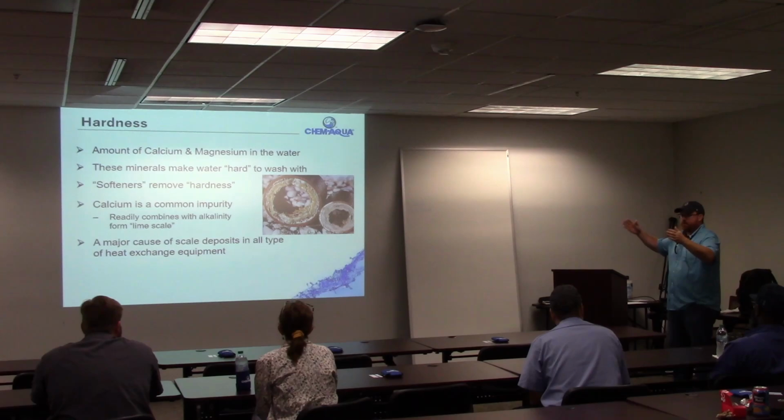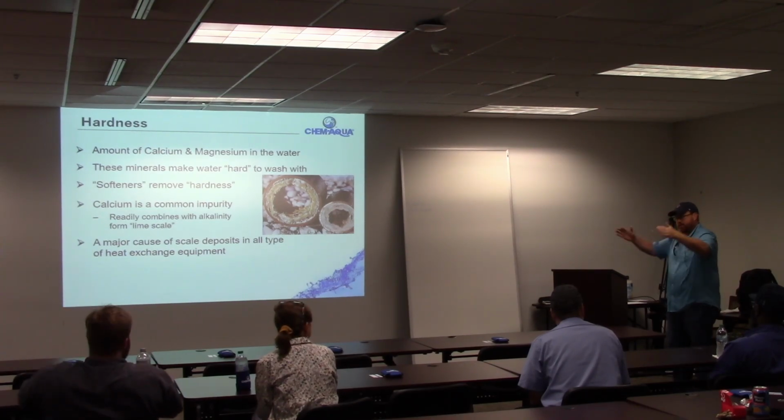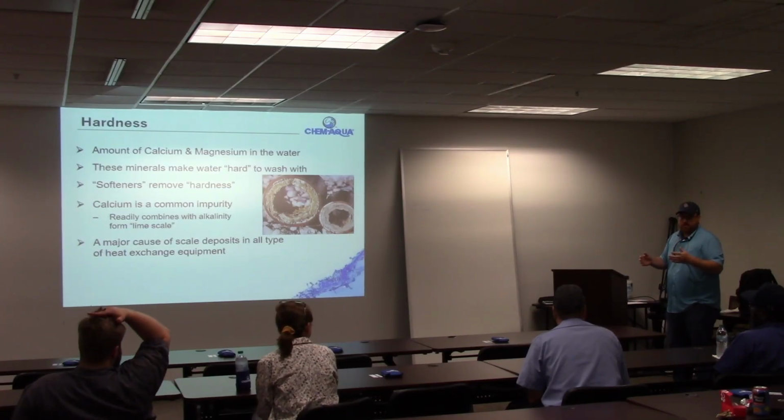If the fan speed is full out, that water curtain going through the fill is going to be pulled inwards. As your load drops off, that water curtain goes back out because the fan is not inducing airflow at as high a rate. So the outer edges of your fill end up having intermittent wet and dry conditions, and because of that, you're going to have evaporative deposits that build up on the outer edges of the fill.